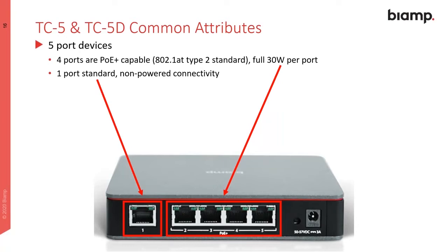Let's say you have a Tesira 40 DAN, or a Tesira 40 AVB VT, you can just connect the AVB port to that desired port. The AVB is capable of doing 128 channels by 128 channels, which is basically equal to 64 streams, which is similar to the Tesira Forte.